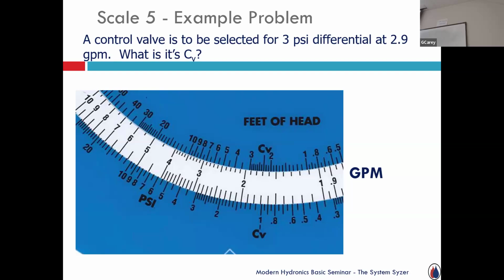So he's probably got a smaller orifice, creating that 1 pound pressure drop. So that manufacturer says, hey, my CV's 20. This guy says I'm 40. Now, when you're talking to the industry, it doesn't know either one, but when you're designing and trying to provide performance, that's where it becomes important.